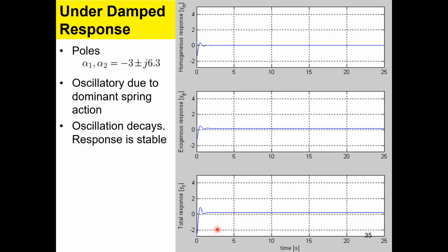So if you ask me whether this is a good design for a shock absorber, I would still say no. Because if you look at the timeline, it's just a couple of seconds, not enough. So we need this oscillation to go on maybe some 3-4 seconds at least. And there should be some deflection over here, not a very small deflection like this. So it is subjective what you really want, but certainly by arranging the components here and there, you should be able to do that.